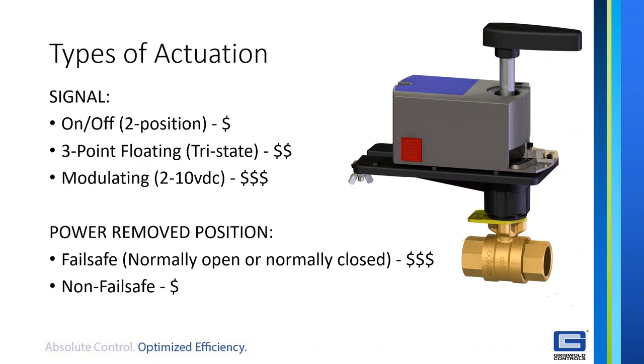We did actually look at specs and at how all of the actuator manufacturers were shipping things. Did they believe it was normally open or normally closed? It was about equally split. The actuator manufacturers are doing it two different ways, so there's really no industry standard. For Griswold, we ship in the normally closed position, because our low torque seal performs better if the valve is left sitting in the closed position. So for Griswold, we will always ship it normally closed if it's fail-safe.